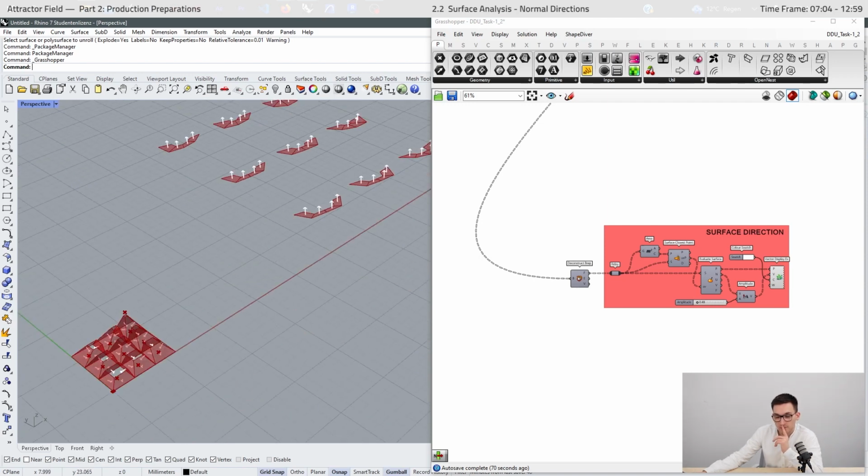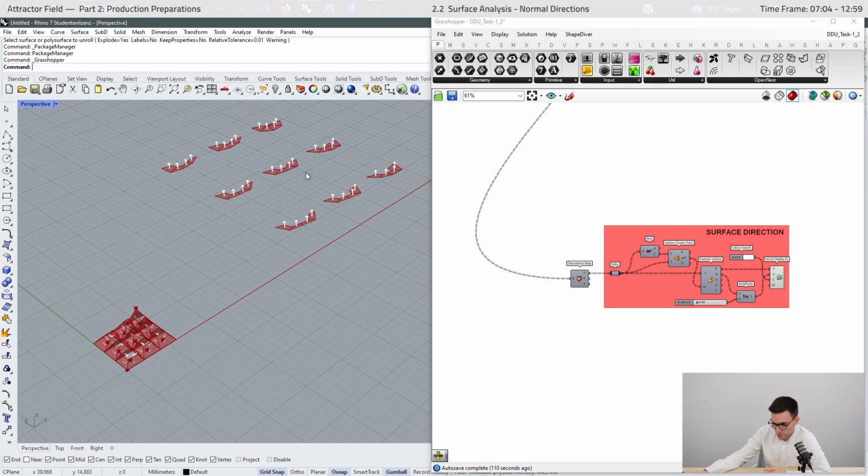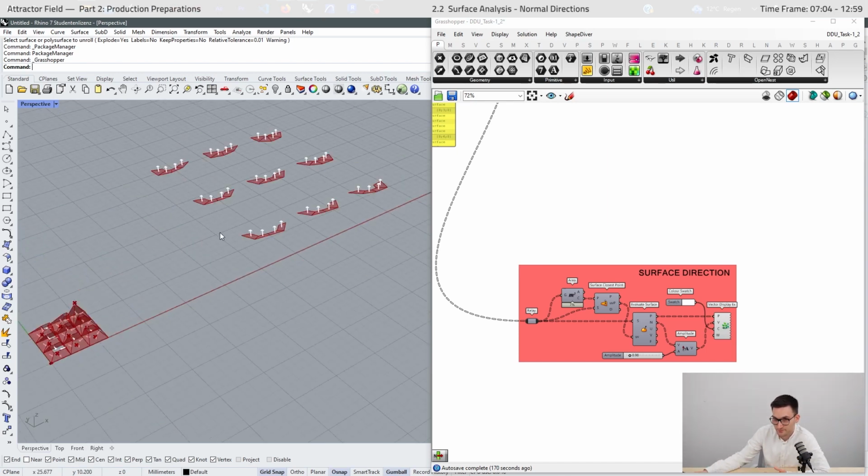If you want the text and markers to be visible, the arrows on the 3D geometry must point outwards. If you don't want the text and highlights to be visible, the arrows should be pointing inwards. In this case, it can be the other way around. This is important to note, otherwise we won't have any information later on how our surfaces are unfolded and in which direction we have to fold.